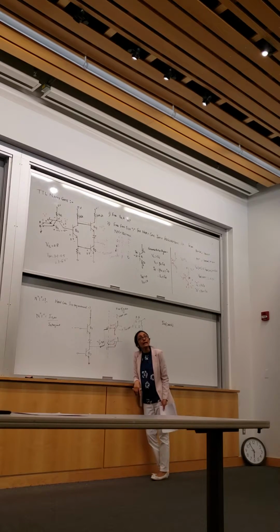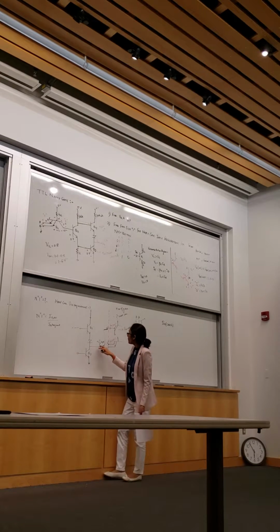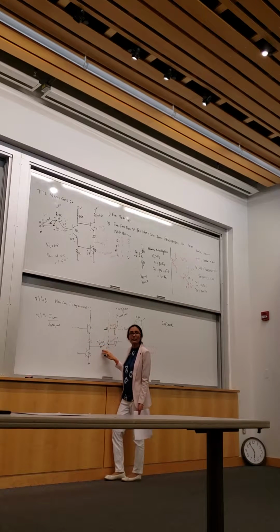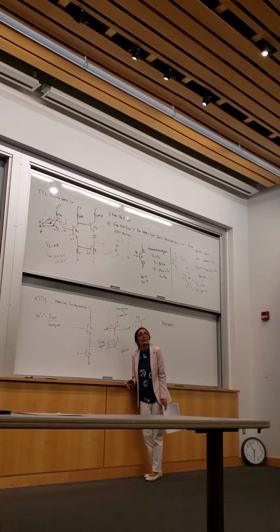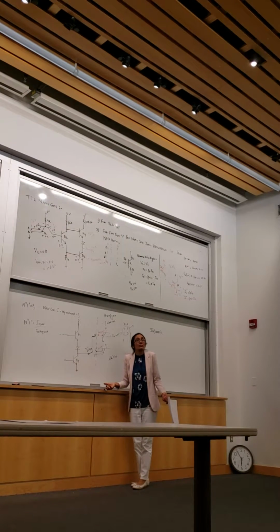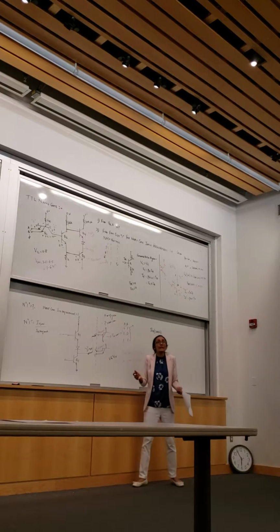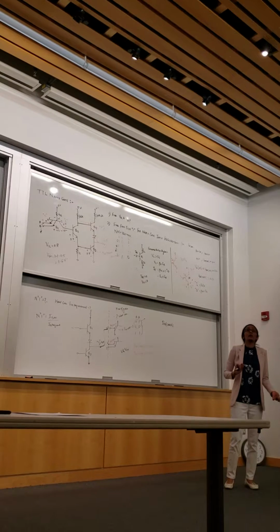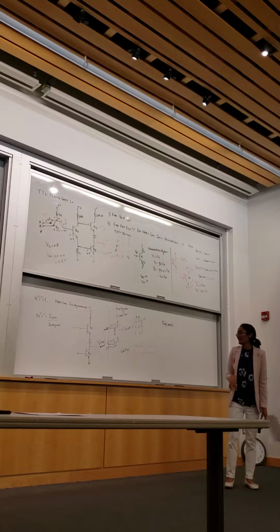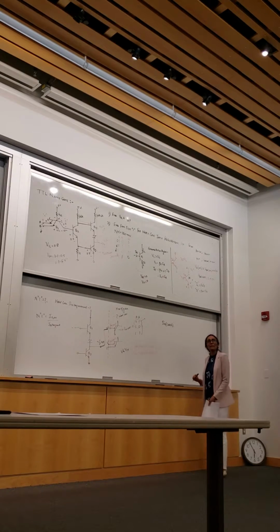Okay. Now we are looking at a maximum value. You know why? Because if the current is high, you are drawing more current, right? This voltage is going down. If this voltage is going down, it can go below VIH. And what happens if it goes below VIH? You're in the forbidden range. Your gates will not be able to detect whether you have a logic 1 or logic 0 at the output. You follow it or no? Yes or no? No in the middle. Okay, but let me just complete the problem. Maybe you'll understand it better.